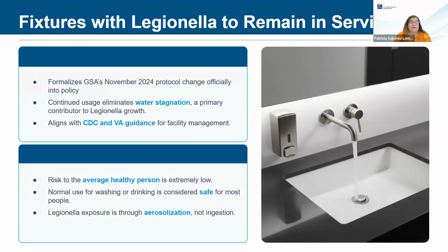Fixtures with Legionella will remain in service. Again, we're just stressing that this is a change from where we started. In our policy, we formalized GSA's November 2024 protocol change, officially signed into our policy in 2026. We're continuing usage to eliminate water stagnation. We can't stress that enough. Moving that water is very important, and it's where you can help us: using those outlets, getting that moving water as we all return to the office. Stagnant water is a primary contributor to Legionella growth, so we can help with that on our day-to-day.